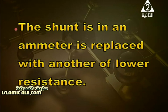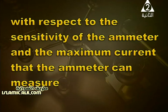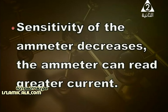What happens when the shunt in an ammeter is replaced with another of lower resistance? Okay, with respect to the sensitivity of the ammeter and the maximum current that the ammeter can measure, what happens to the sensitivity if the shunt is replaced with another of lower resistance? Sensitivity decreases, and this means the meter can read greater currents.